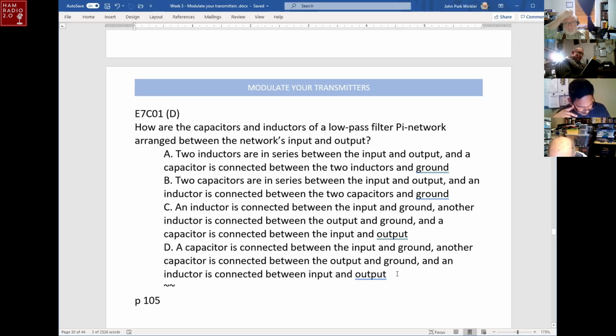And I remember this basically from the standpoint of the old brute force, high voltage power supplies in tube type rigs, because you put the output of the voltage rectifier across, put a capacitor across the output of it, you put a big heavy multi-Henry choke on it, and you put a capacitor on the output, and it filtered out the AC component and left just the pure DC, supposedly, on the output.